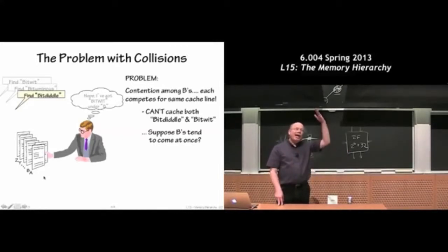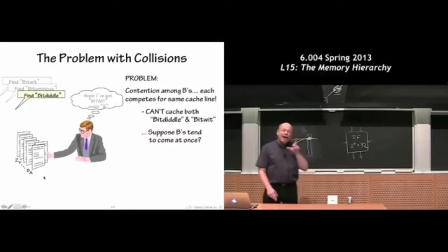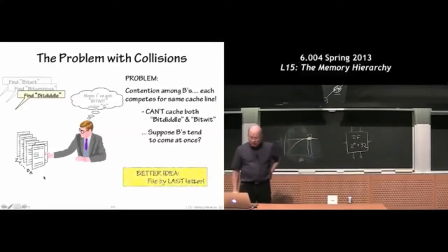I want to make sure that most of the addresses that are coming in sequentially map to different slots. And remember there's a pattern to these addresses that are coming in. I want to look at that pattern, understand what it is, and try to figure out a mapping function so that most of those addresses will map to different slots. And then I can get away with a single comparison.